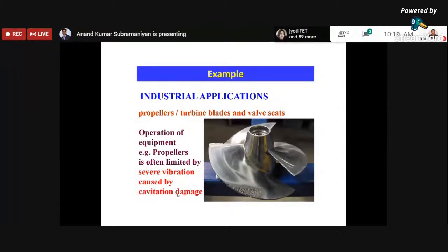You can see this cavitation damage which happens on this particular surface because of the pressure difference, and it is also actuated by the silt particles. Eventually the material will be removed, and if it is not properly inspected, we can expect the material to undergo failure, right? Which can cause significant, catastrophic malfunctioning of the system.